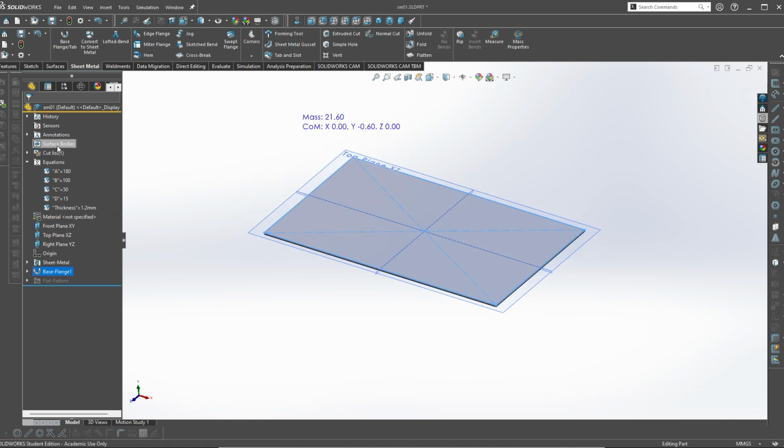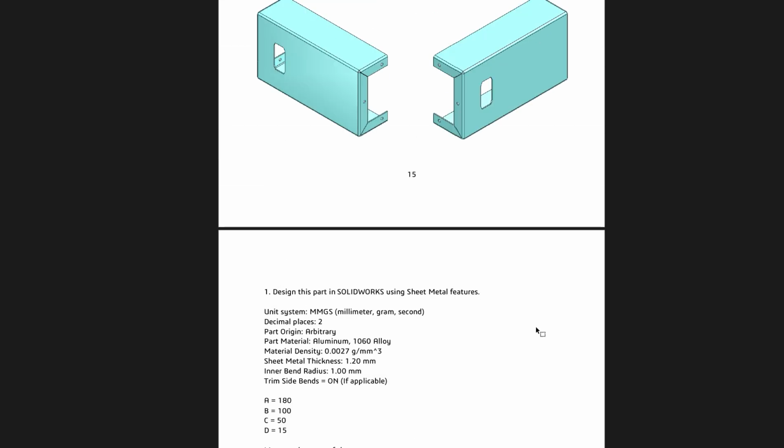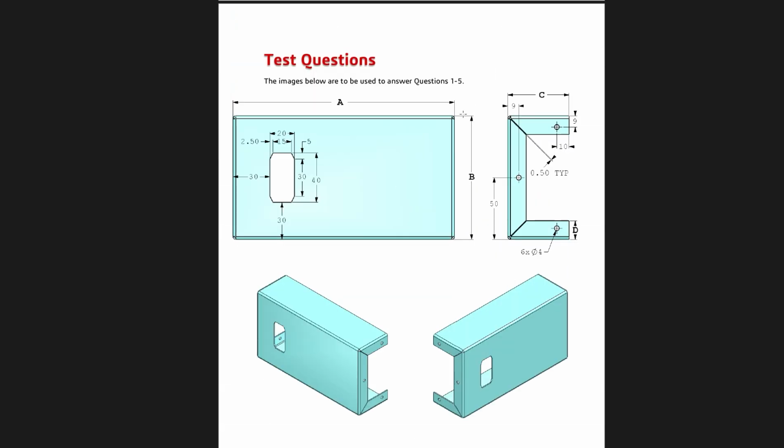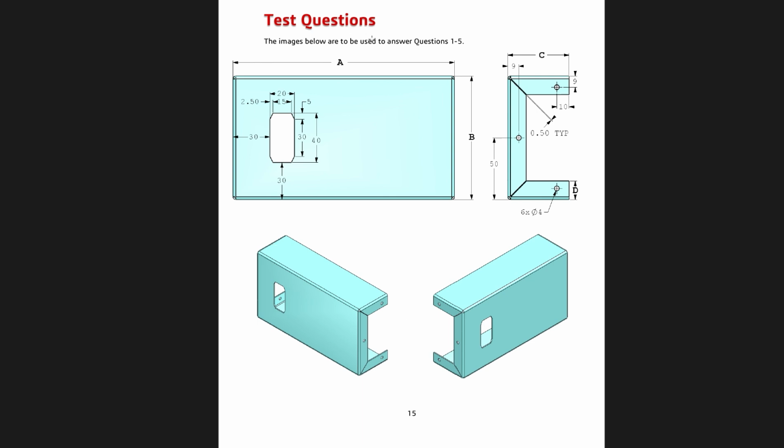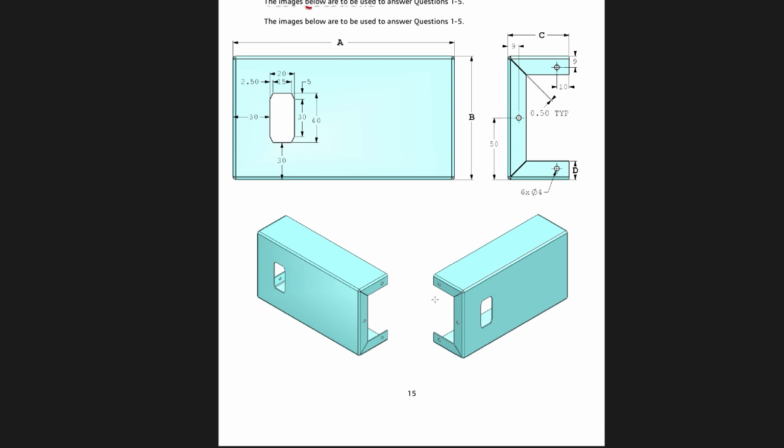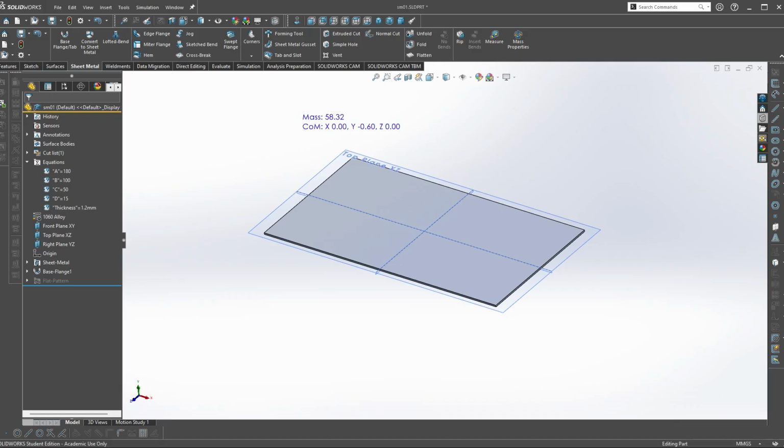And while we're at it, let's go ahead and set our material here to 1060. Rebuild, and we should have that number 5832. And then we'll keep going. So probably going to do a virtual edge just to keep our dimensions straightforward here. And probably the best approach is to put the sidewalls up and then do the 3 end tabs just to make things easier for fitting in these, I guess you could call it a mitered edge. And we have a 0.5 gap between these where these bends come, so those cuts need to be accounted for.